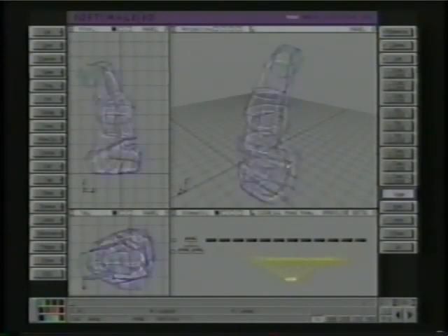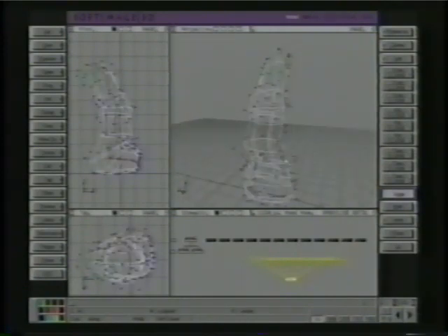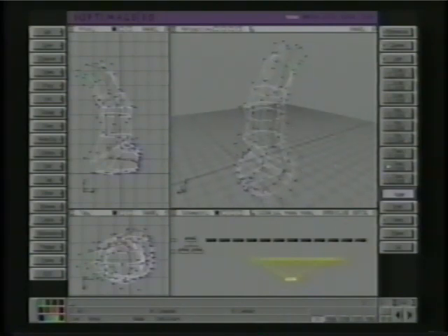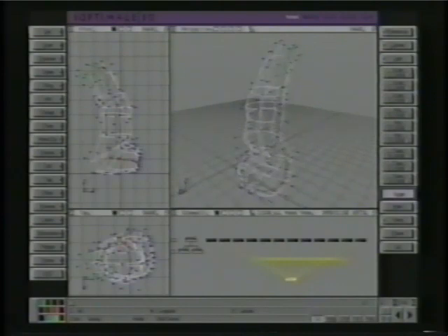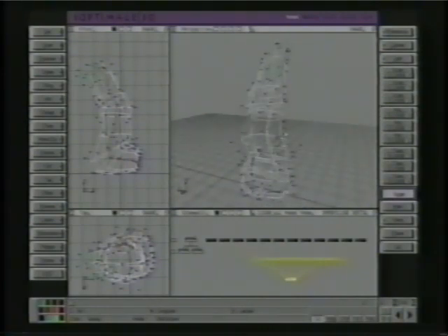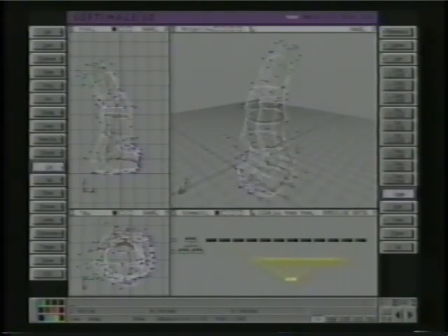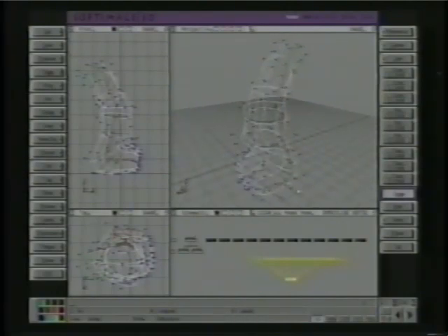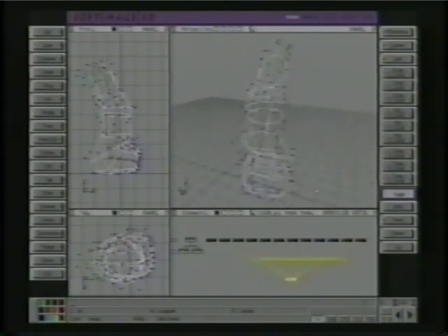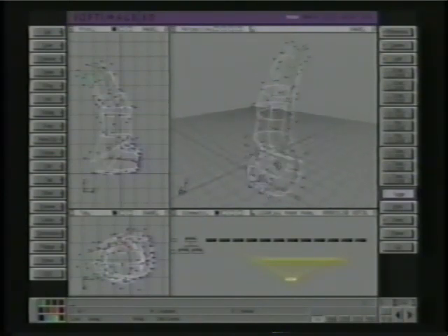Also, if you should edit the envelope in any other way other than inversing it or translating it, you'll get into trouble. Upon the next refresh, it'll jump back to how all the generator curves are positioned and so on. So if I make a bunch of changes here, next time I refresh, then those will jump back. And so you have to be careful of that, or else you'll learn it the very, very hard way, like I did. I'm sure many other people did.